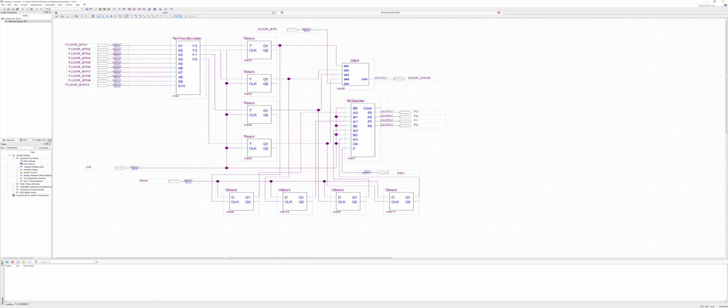So the goal of this project is to implement a schematic of a digital logic controller for an elevator. And the diagram must take in 10 inputs, which are the floors of the building, and have the signal of the button pushed stay high until it reaches its destined floor. I have to implement clock cycles within the elevator, with the closing and reopening of the door lasting 5 clock cycles. The elevator travels at a speed of 3 clock cycles per floor. I must see that these conditions are met.